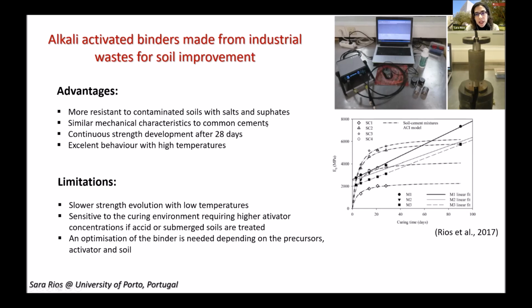We also monitor the strength and stiffness evolution of these binders with ultrasonic transducers, as shown in this photograph. Soil cement mixtures based on Portland cement generally increase up to a certain point at 28 days, and then they remain constant. But these alkali activated binders, generally the low calcium ones, tend to increase the stiffness and strength further beyond the 28 days. So this can be an interesting property of these materials.